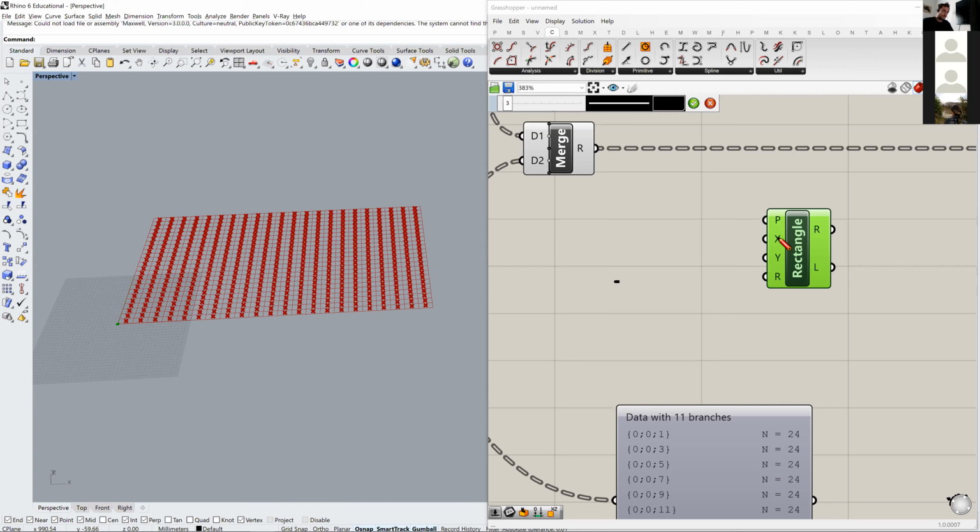Defining this kind of geometry by X and Y domain scale, let's say, means that this is the center of our plane, which is 0, 0. And now I'm drawing a rectangle in the domain which is by default -1 to 1, and Y is -2 to 2. That means that our rectangle has scale between -1 and 1 and -2 to 2. And basically this is the rectangle we draw.